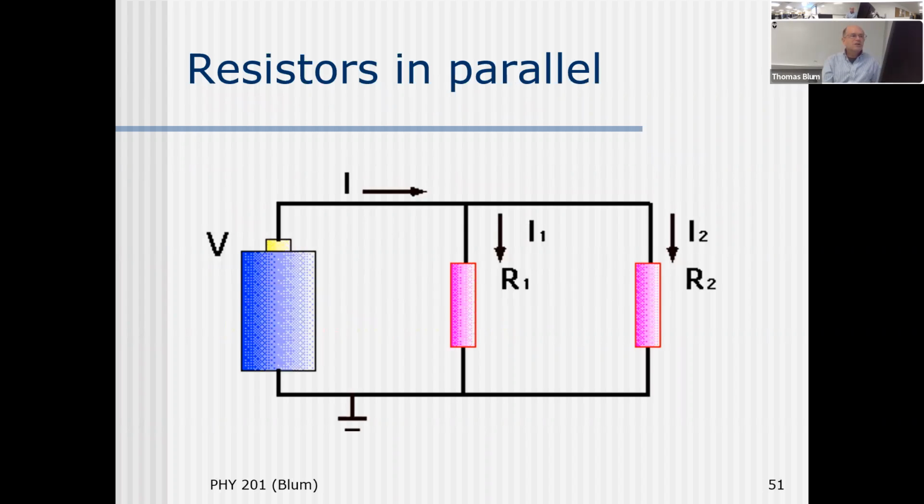Okay. So here is a drawing with 2 resistors in parallel. We will say that 2 resistors are in parallel if there's a wire on the top, or there won't always be the top. If there is a wire connection on one side and a wire connection on the other side, then those 2 resistors are said to be in parallel. So you look for the wire on one side and the wire on the other side. That wire can be connected to other things. But there's a wire here. A voltage doesn't change along a wire.